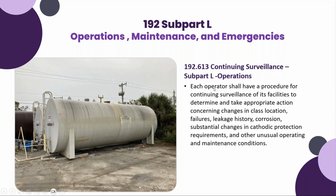Regarding this, it's my favorite one, and this is the most ignored one. It's continuing surveillance. It's overlooked, and this is why I bring this up. And I'm going to read this one because I think it's very important. Each operator shall have a procedure for continuing surveillance of its facilities, determine, and take appropriate action in the class location, failures, leakage history, corrosion, substantial changes in CP requirements.